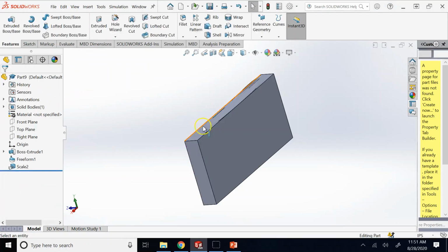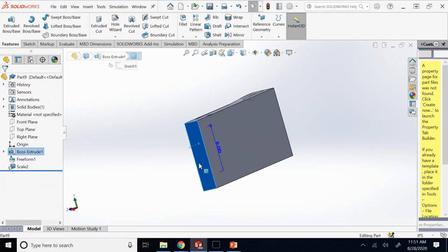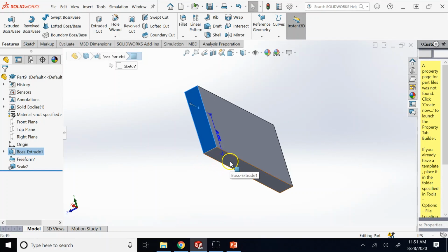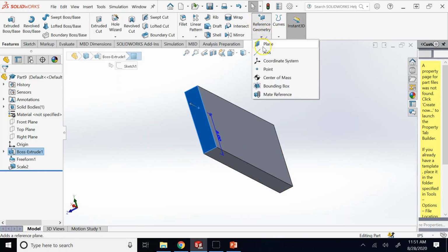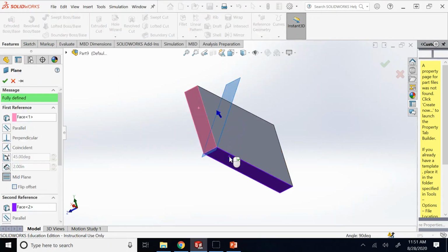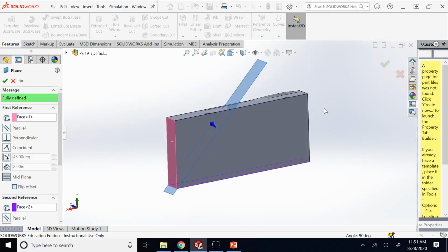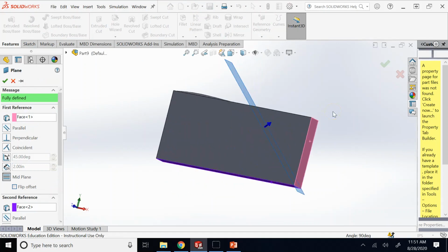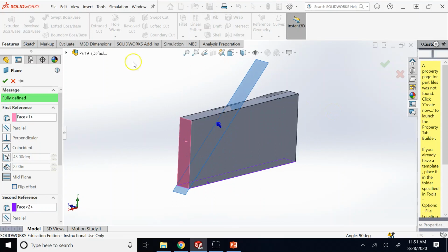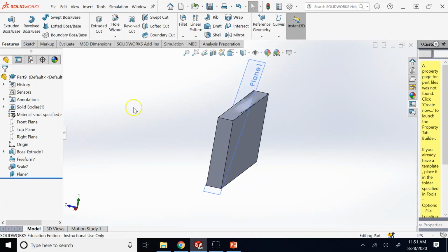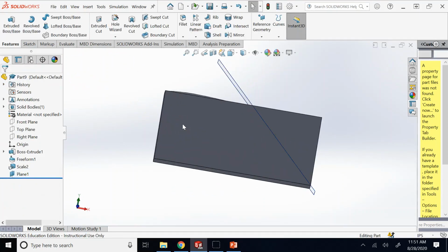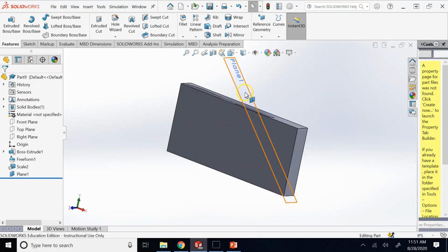No, it does not like it, so maybe I choose these two guys. Let's see, so I choose that plane and this plane, and then I use the plane that cuts the angle between them in half, like that. Okay, and I can even give it an offset. If I don't want this directly, I will create an offset version of that.